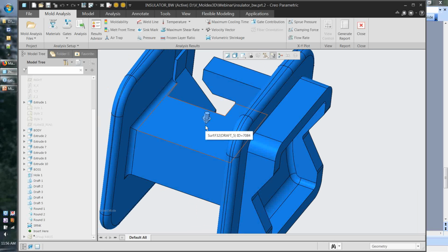middle of this space on the side that was selected for the gate for this simulation. Just to give us some results, we just arbitrarily, as we did in the earlier part of the demonstration, picked a gate location, gave it an orifice diameter, and away we go. But we see that the gate information is stored with the file set that is saved, so that it is known again later where the gate for the analysis was located.